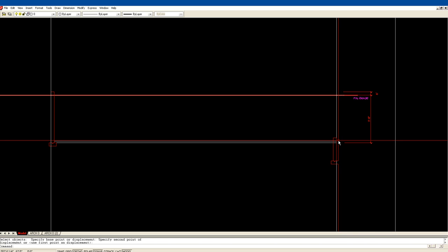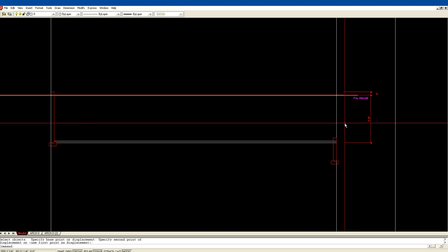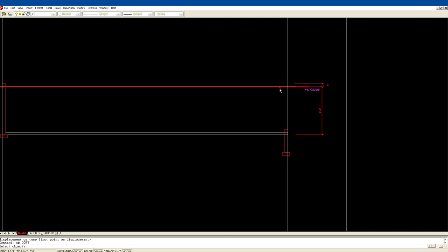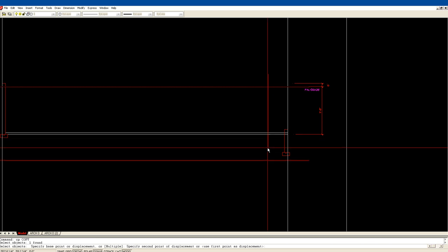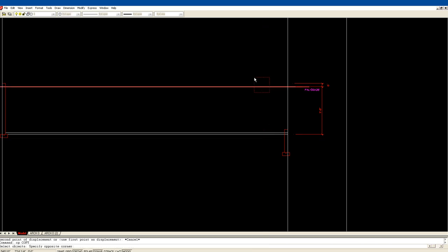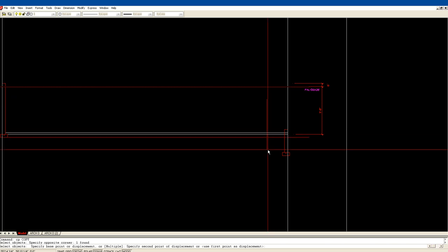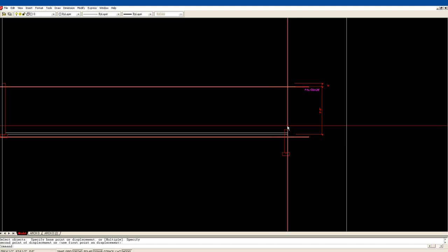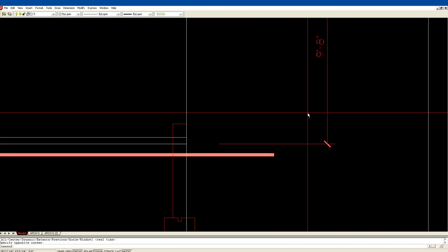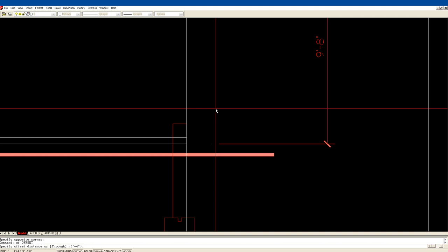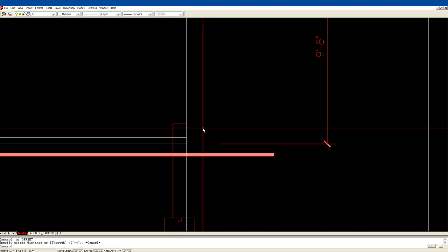I'm going to cut the concrete wherever I have a door opening, but I still want the door to be 8 inches above. So I'll show you what we're doing here. We're going to copy this line because we need it there. We're going to put it down wherever we want, and wherever he wants, somewhere around there. Now we have lots of concrete showing there. Let's offset 8 inches. Actually, that would be that line right there.